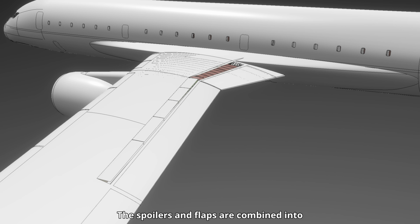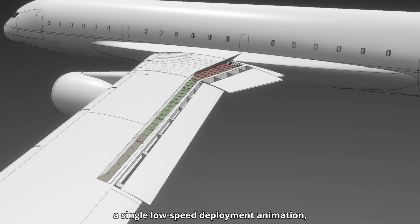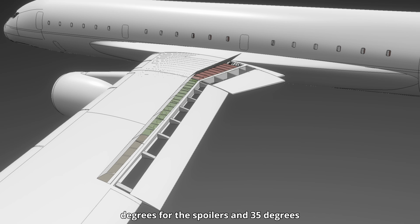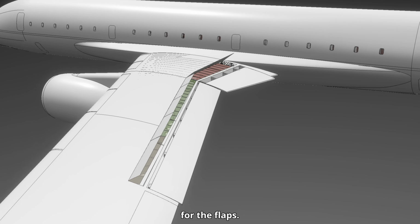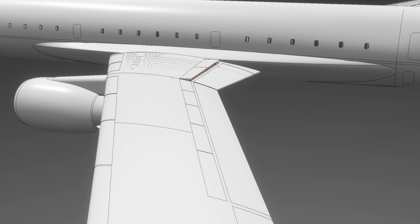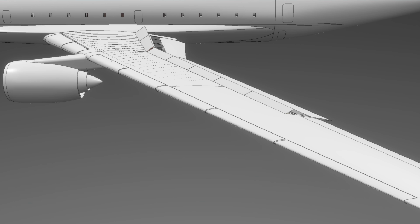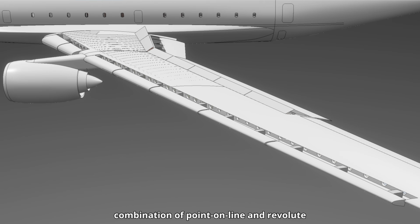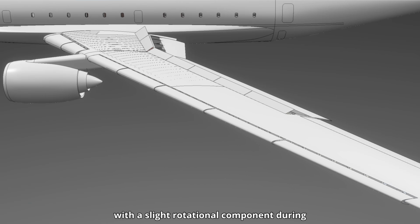The spoilers and flaps are combined into a single low-speed deployment animation, using revolute connections for the spoilers and point-on-line for the flaps, with deflections of approximately 30 degrees for the spoilers and 35 degrees for the flaps. Finally, the slats are modeled using a combination of point-on-line and revolute connections, allowing forward extension with a slight rotational component during deployment.